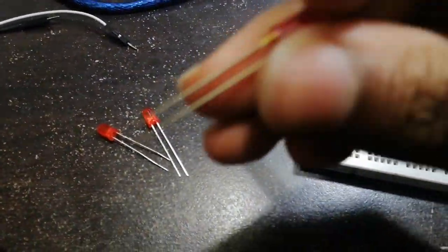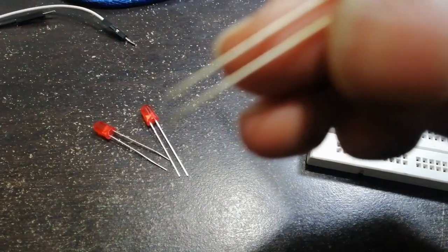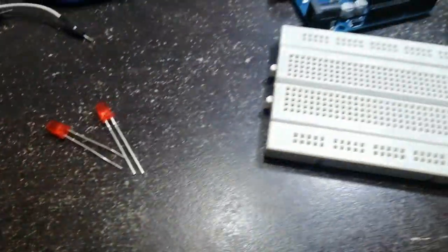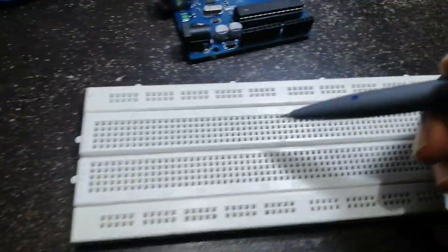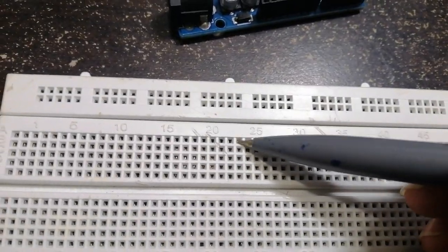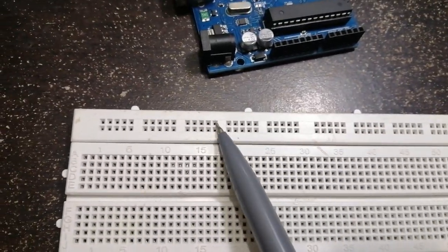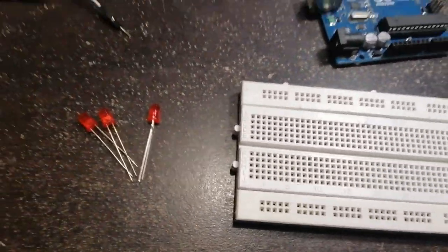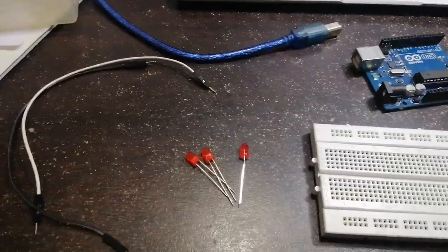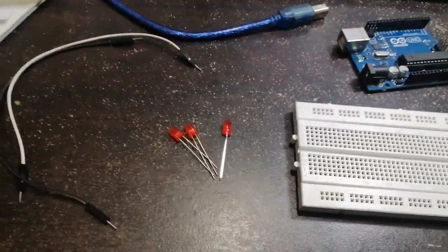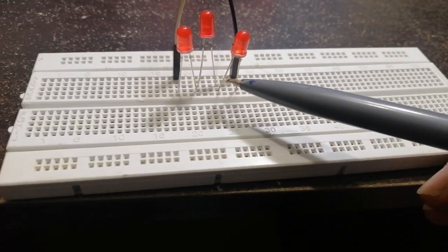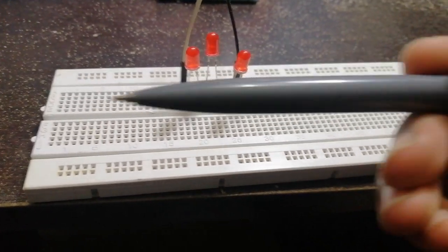So as you all know, the LED has two ends. The longer one is positive and the shorter one is negative. And in the breadboard, the pins are lined up like this, and these pins are lined up like this. So now I'll make the circuit a series circuit and I'll show you how it looks. Okay, now I've finished the circuit and all of the positive terminals of the LEDs are facing this direction. The negative ones are in this direction.